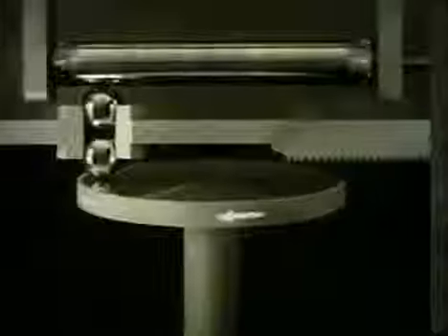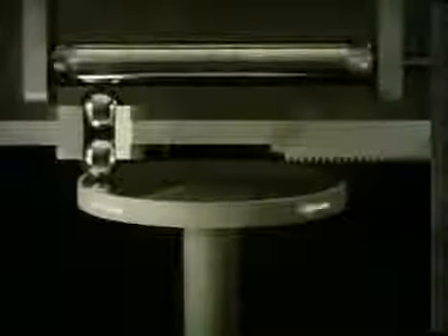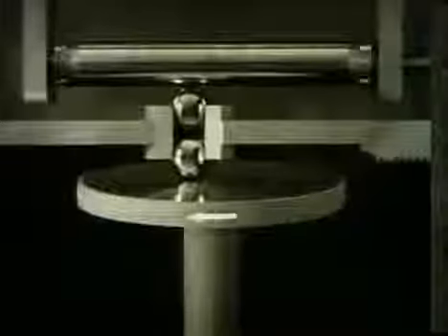The rotating disc, through friction, turns the balls and the roller. When the balls are near the edge of the disc, the roller turns at maximum speed. Roller speed decreases as the balls approach the disc's center. And, at center, roller speed is 0.